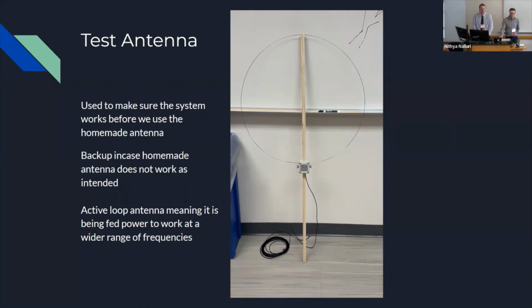5-volt. Okay, so I thought the 12-volt ones had regulator problems and fried. Yeah, 5-volt ones were better, but then you have more of a risk of getting noise from your power supplies. Yeah, because our overall system is going to be working with 5 volts in general, even with our passive loop, so we wanted to keep it consistent with what we're working on.